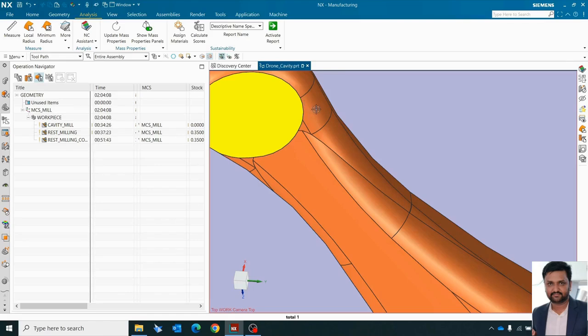Let's consider, whatever region my cursor is kept on, that region is 1 mm. If I use a cutter with diameter 4, then the radius will be 2, then it will not machine that particular region. So I have to take 2 diameter as my finishing cutter.